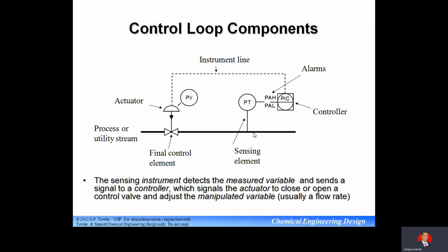So indicator and controller, these three things are there. See the nomenclature: the first letter Q for quantity, F for flow, L for level, W for weight, P for pressure, PD for pressure differential. That type of nomenclature is used in process instrumentation systems. Okay, so here, to summarize, if you see all these systems